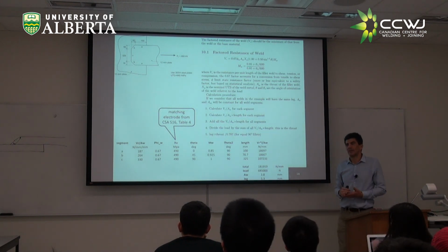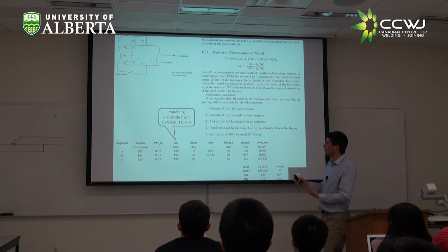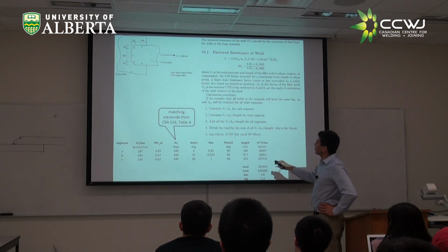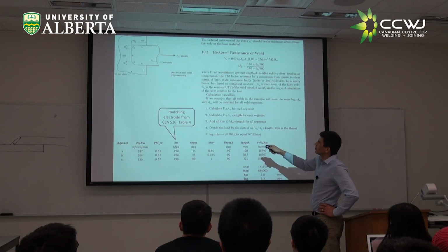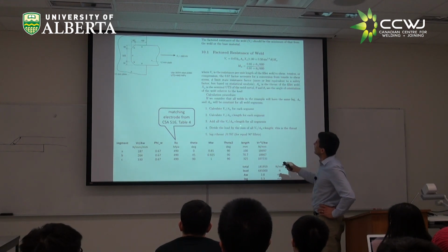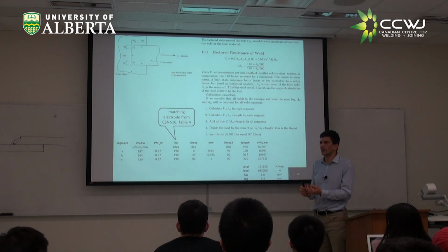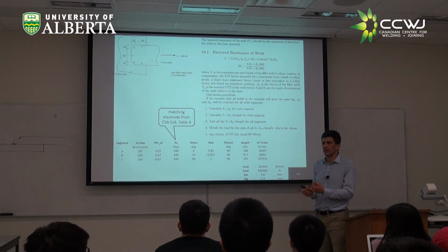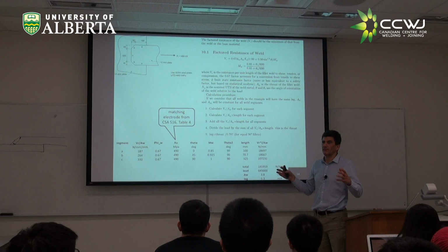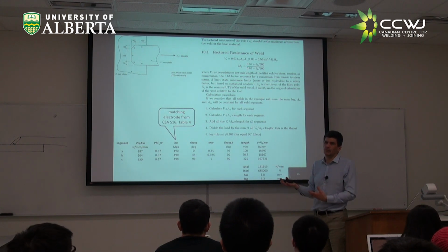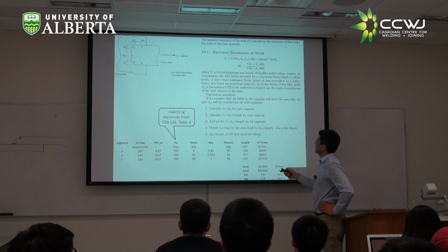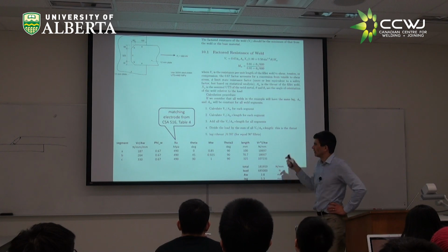So I multiply this strength per unit length and unit area by the length, right? So then I add them all up. And then, I know my strength per unit length and unit throat. I multiply by the length, so I would have the strength per unit throat, right? So I have the top load. I divide by my strength per unit throat, and I get my throat. And that's what I do. So divide by the sum of these. This gives us the throat.